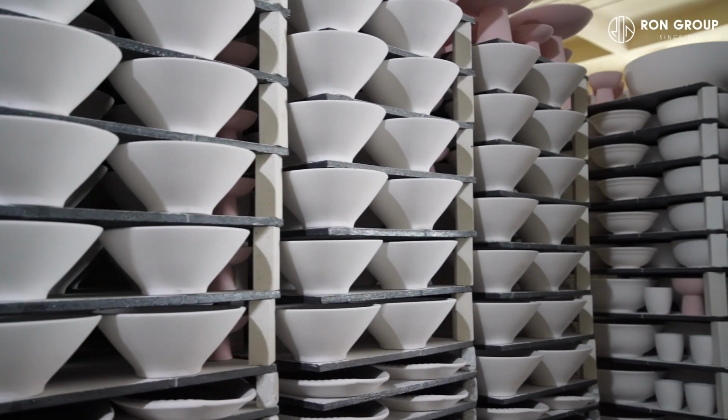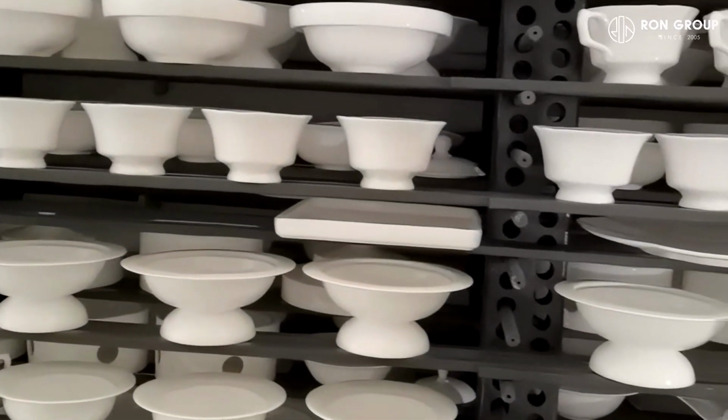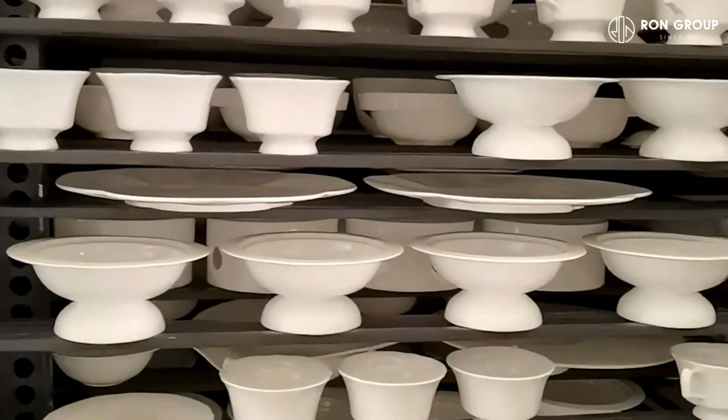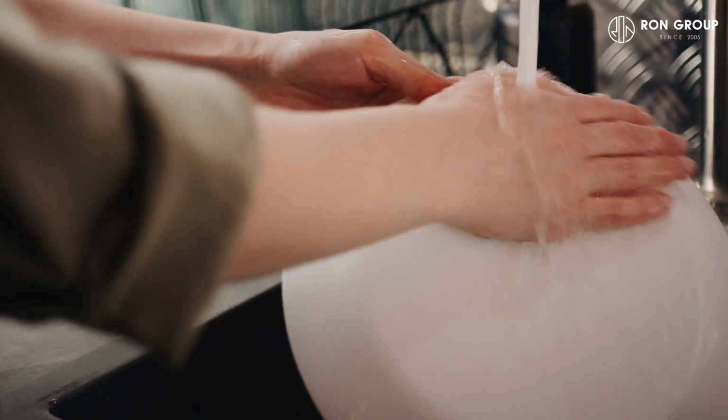High temperature porcelain refers to porcelain that is fired at high temperatures, about 1200 degrees, after the porcelain body is glazed. At these temperatures, the glaze fuses with the porcelain body. The porcelain is very fine and relatively hard, and the surface hardness is high, so it is not easily scratched, and the sound is very crisp. The high temperature porcelain surface glaze is smooth and pure white, and the water absorption is very low, so it is easy to clean.